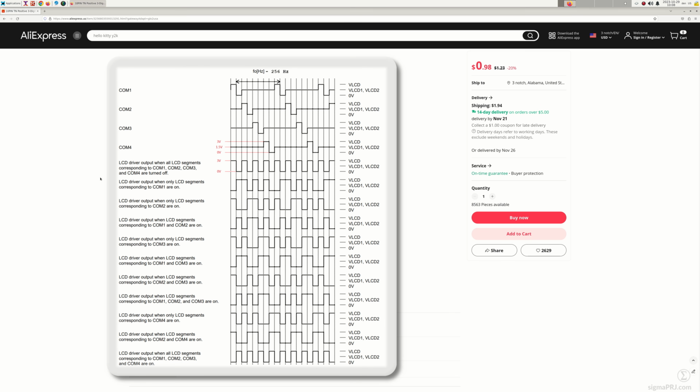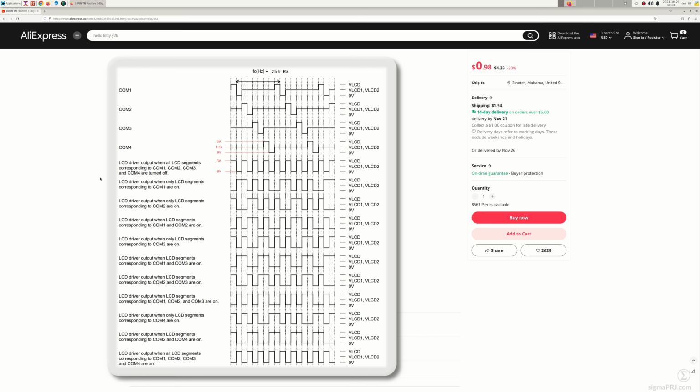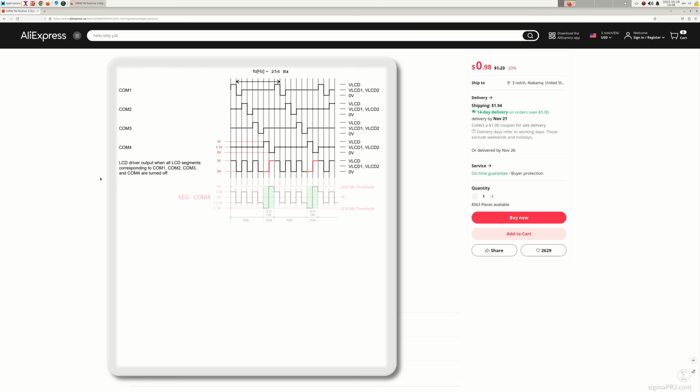In case you would like to switch off all available LCD segments for a specific pin, we just apply in-phase signal in relation to our command line strobes. And, as a result, we'll have the following voltage difference between segments and the command line. As you can see, AC voltage amplitude will be below threshold level. This way all segments will be switched off. And if you would like to switch on specific segment, then we can apply signal inverse operation on a specific time section. This way voltage difference will exceed defined threshold level. Hence, the segment with such voltage difference will be ignited.